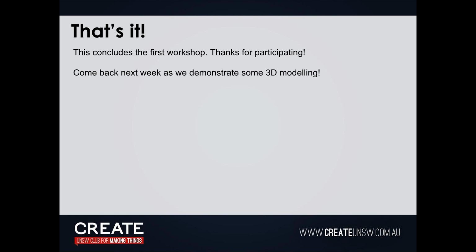So we'll make a mid plane. So that's one plane. That's the other plane. Oh, I selected the wrong plane. We're trying to duplicate these. I want to split it in half and then duplicate the top and bottom. So we'll go construct mid plane. That's one plane, and here's the other plane. Now it knows that that's the center. Next we go split body. You select your body. Next is a splitting tool, which is right there. Hit OK. Now those 2 are split.